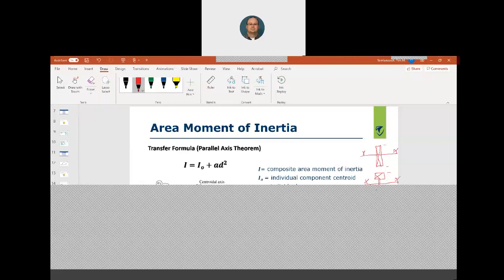It's very interesting. I'm taking material away, but I'm actually making this stiffer because I have an object that's away from the composite centroid. I have an area that's away from the composite centroid, and it's actually adding to the moment of inertia when I put a load against this. So this is why these I joists and things come about. Believe it or not, it's a very interesting thing.